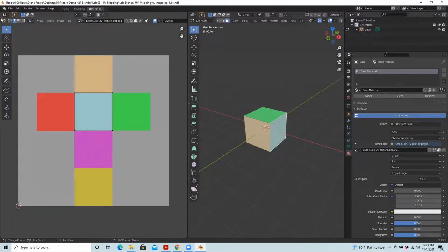And you have a tool set actually in that tab. So right now I'm in the select tool. And this is actually really similar to edit mode, because when you're in the select tool, you can choose what you're selecting. You can choose faces or the edges, points. I'm going to choose the edge selection. And then what you're going to see if we experiment for a minute is that you could click to choose either different points or different edges. So in my case, I have that top edge selected, and then I could make movements to edit the map itself. So after selecting that top edge, I'm going to switch to the move tool itself, and then I can pull on these arrows to move in different directions.